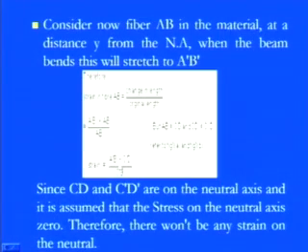So we have A dash B dash minus C dash D dash divided by C dash D dash. Now you see our main conclusion for the strain component is focused on what will happen when the strain component is there. That means A dash B dash is nothing but the total deformed part along the line AB. C dash D dash is the new location for the points on the neutral axis, and when both are compared, we can get the strain component.